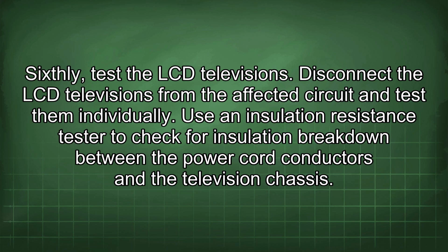Disconnect the LCD televisions from the affected circuit and test them individually. Use an insulation resistance tester to check for insulation breakdown between the power cord conductors and the television chassis.